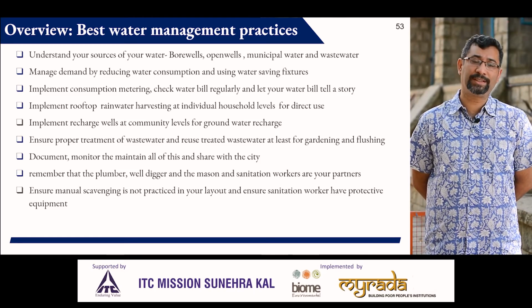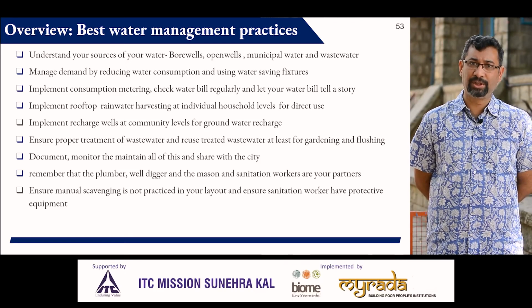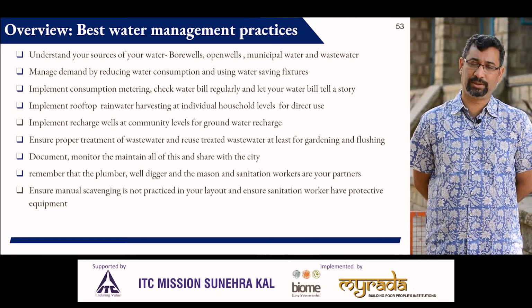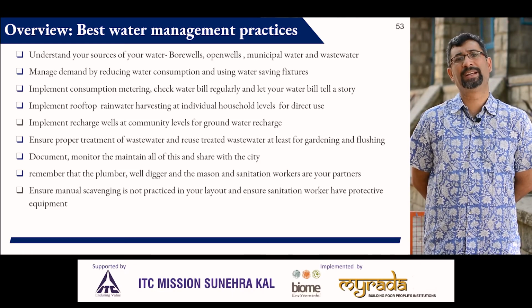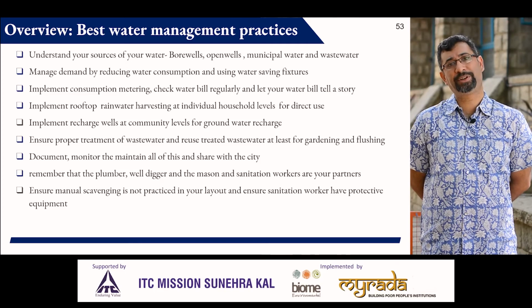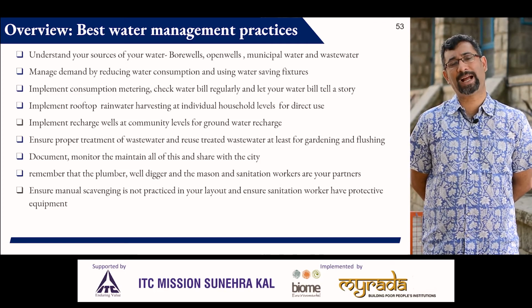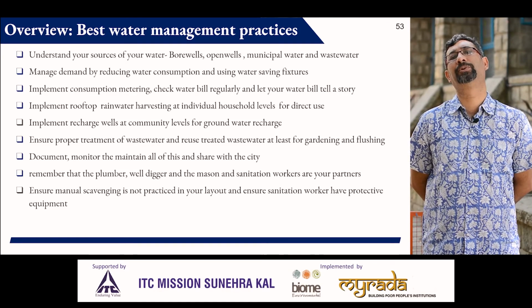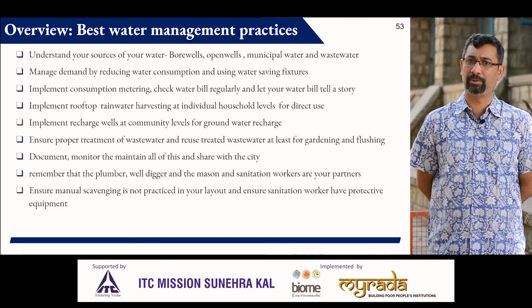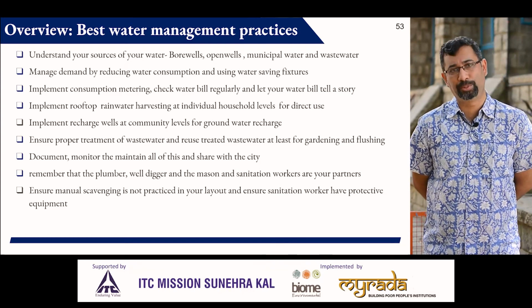Similarly, water that's falling on clean roads or water that is not being able to be stored in storages from rooftops can all be led to recharge wells. So you can capture rainwater from common catchments and private catchments which you cannot store and ensure that you recharge groundwater, because we are all dependent on groundwater either through wells or through bore wells.